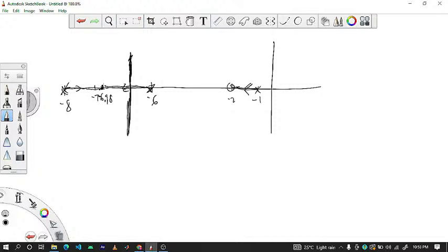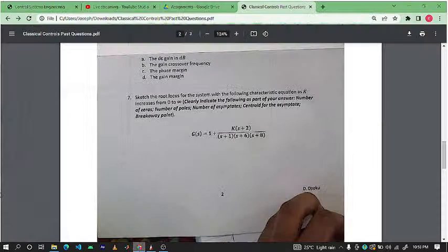And I'm saying that since the root locus is symmetric, it means that there's one zero here, there's another zero down here. So when they meet, one of them will move like this. It will move asymptotic to this one, to infinity. This one also moves to infinity. And there you have it. So this is how your final drawing will look like. So in answering the question, we ended up doing everything.